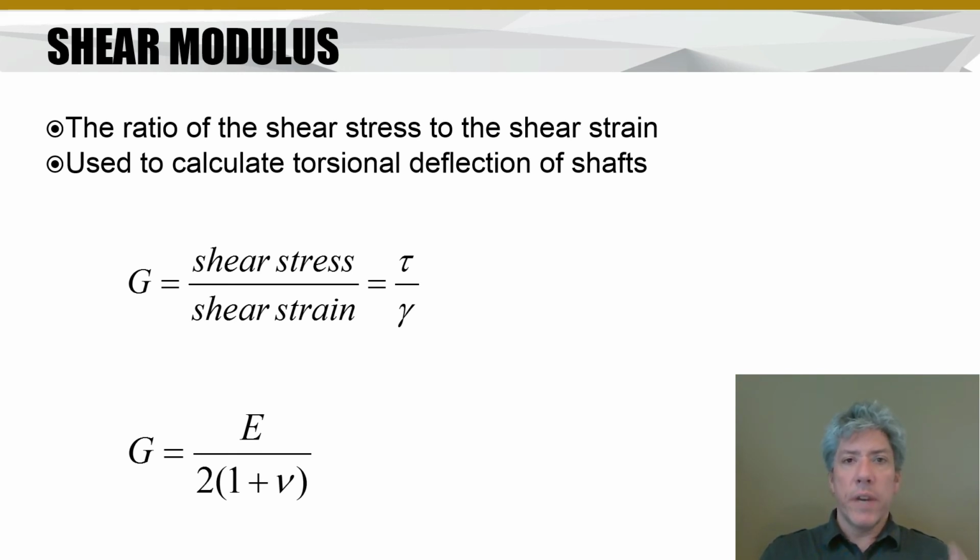Now, this is very helpful when we're talking about torsional deflection. If you have a shaft, and let's say you're putting torque on that shaft, it turns out that the load in that shaft is primarily shear. Now, in the real world, you end up with some other loads, but primarily you mainly have a shear stress in it. And so what happens is that rod or that drive shaft will